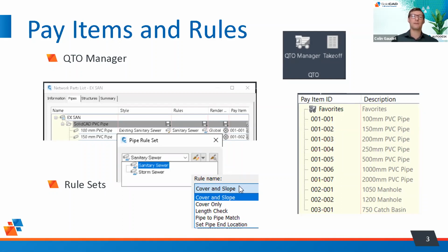It's going to help you offer a max and minimum criteria for each of those, and then flag those things as you're editing those pipes and say, hey, it's actually not following the rules that you've set out for the area that you're designing in. Civil 3D comes with one standard rule set. Chances are you're going to need at least 2 or 3. When you're talking about sanitary versus storm, you're putting your sanitary deeper than your storm, and things like that. So you can adjust those cover and slope options accordingly.